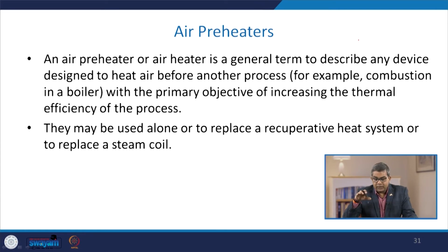all the raw materials or all the ingredients must achieve a particular temperature zone. And if there is a drastic difference with respect to the delta T, there may be chances of a thermal shock, there may be chances of a non-efficient system. So that's why the air preheater, because air is an integral part of the combustion process, so the air preheaters are quite important in any kind of steam generation unit.